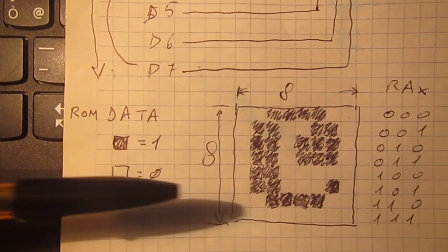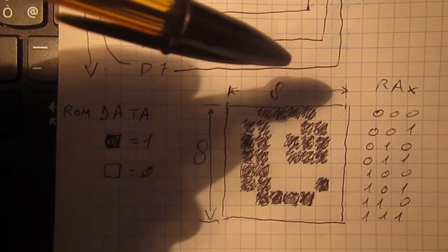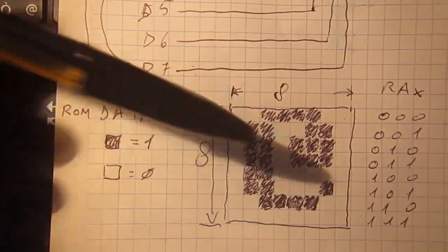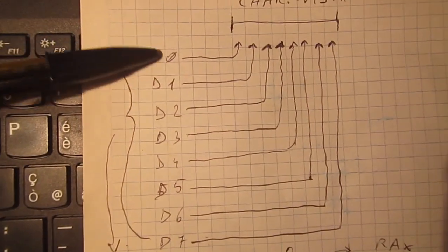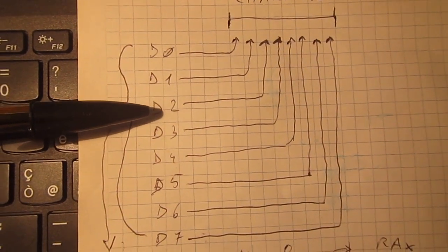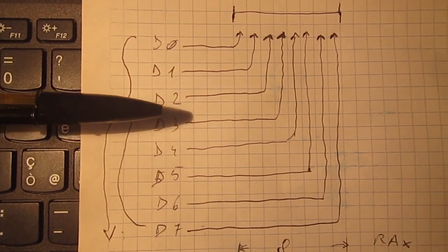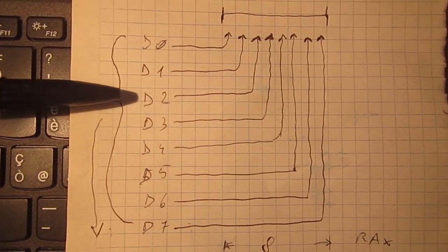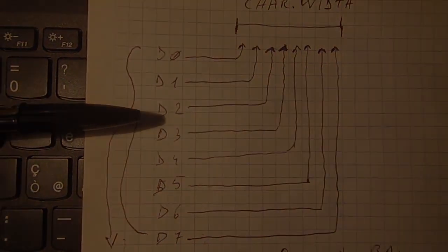So in order to have a complete illuminated column on the screen, what happens is that one of the bits of the ROM is always 1, or the shift register is faulty because the input is not taking the actual bit from the ROM.